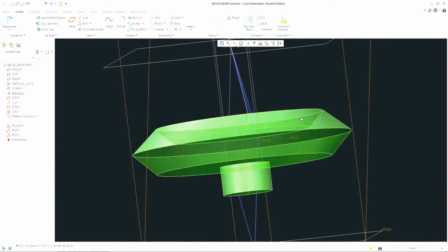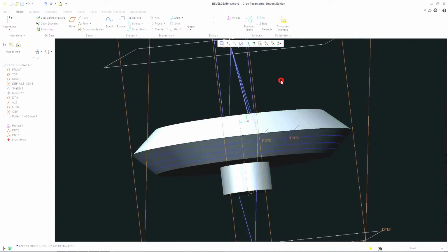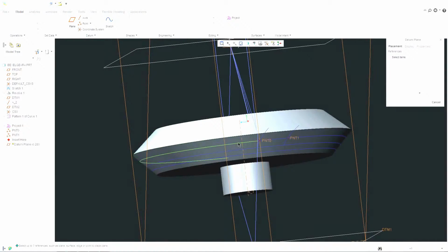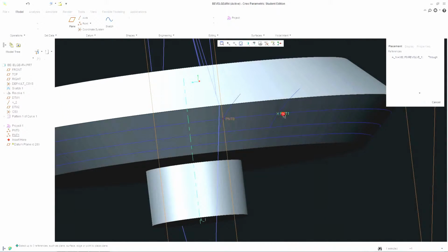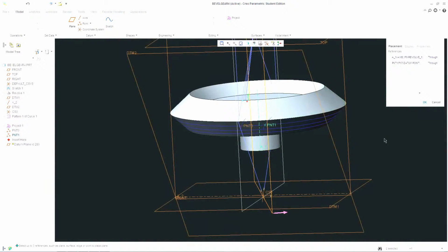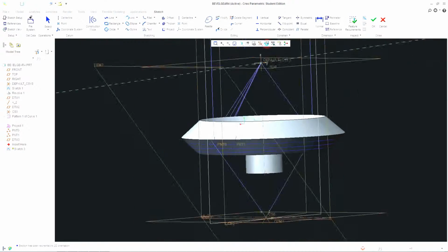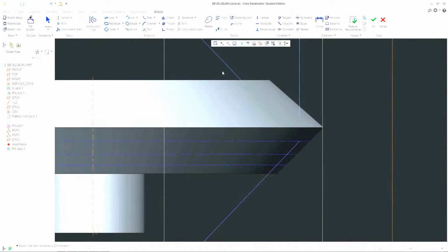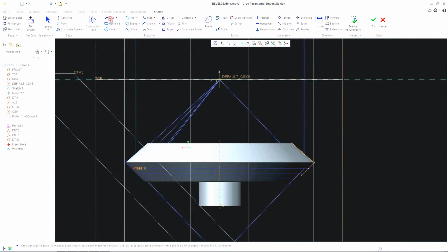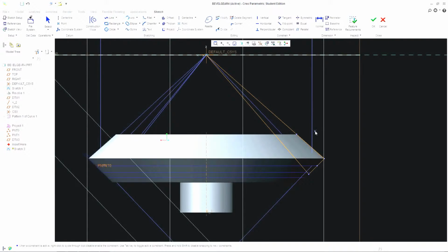And what we're trying to do now is create a cut on the right side. So I'll create a plane, click on the axis, and hold Control and click on that point, and it'll create a plane that is vertical and connecting that point. And on this plane, I'll create a sketch. On here, I will use the project tool to create a line from there to there and there to there. And I'm going to use the line tool to draw that line to the apex and bring it back to there. Deselect and make sure that it's a loop, there's no gap. We'll accept that.